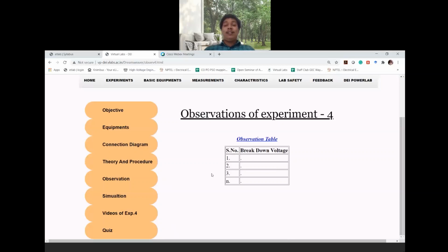So it will have a variance. When it varies over a sufficient gap, it is usually represented in a statistical distribution, and it is seen that it follows the Weibull distribution. There are two parameters of the Weibull distribution, the scale parameter and the shape parameter.